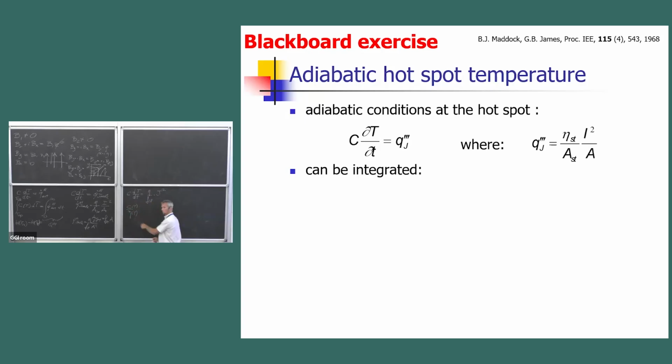The resistivity is a temperature function. I integrate in temperature, and that's equal to the integral in time of the current density. Okay, current density is only a function of time. Now, this thing here is actually the reserve I have, the capital I have, that I spend because of the heat that goes in.